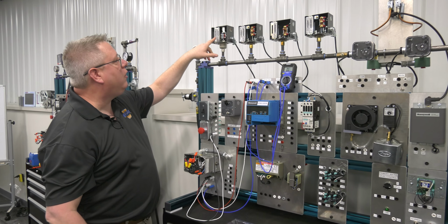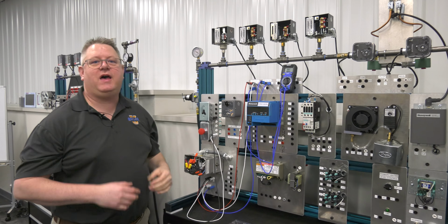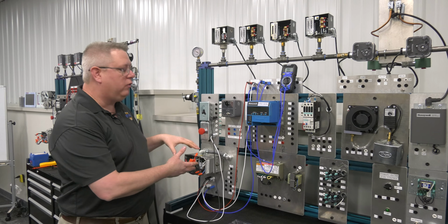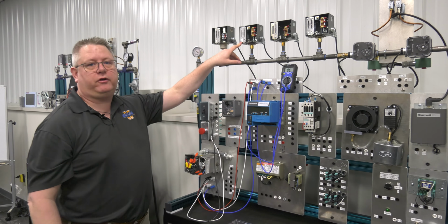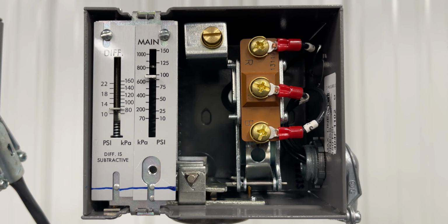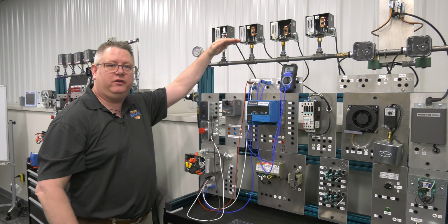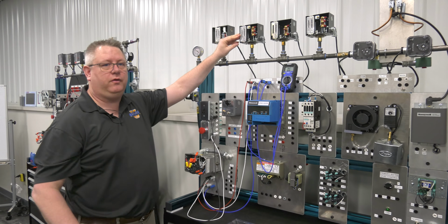The firing rate control, if you look inside, doesn't have a switch. It has a potentiometer with a slide wiper, and that indicates that it's a modulating control, and that's what it does. It modulates and controls the firing rate control motor for the burner. Our operating pressure control can really be thought of as our first high pressure cutout because it doesn't affect the modulation. It simply shuts the boiler down when it gets to a determined pressure and then allows it to restart in most situations once we get below the differential on the switch.